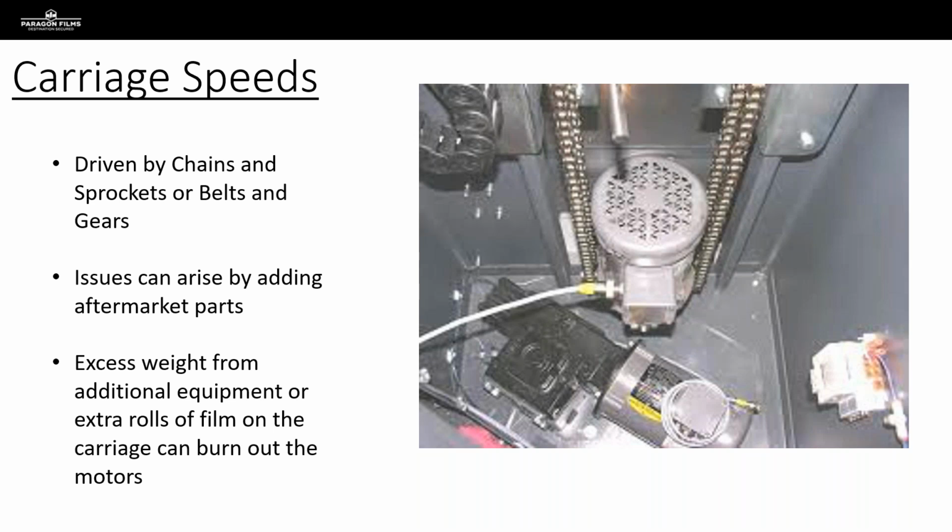Whereas if you were to dial in and really optimize both of those levels, the carriage speed and the rotational speed, you can get the right amount of overlap as well as the right amount of force to that load. And it's important to note that speed isn't necessarily the best answer here, right? It's really about finding that balance of rotational speed and carriage speed, providing that together to ensure that the pallet is secure, or the product on the pallet is secure and well organized.